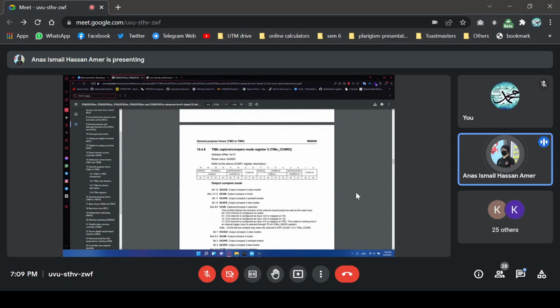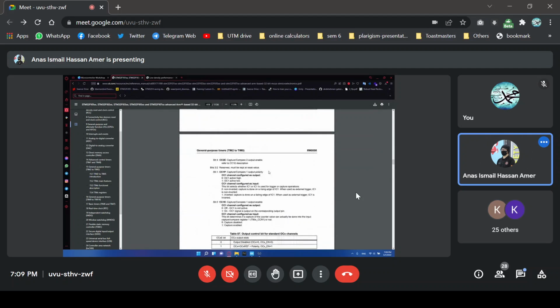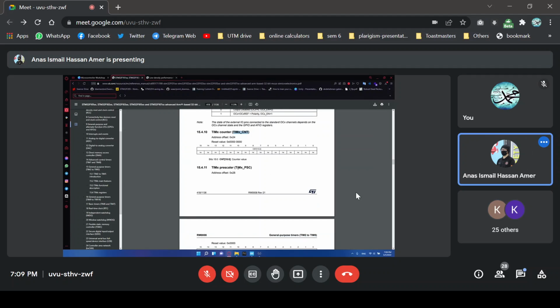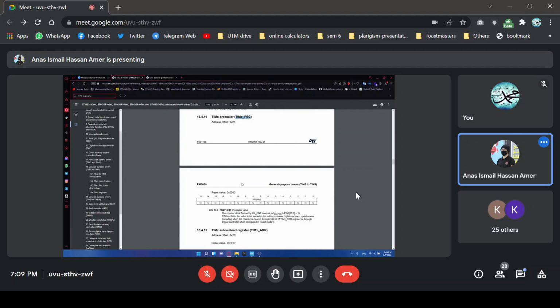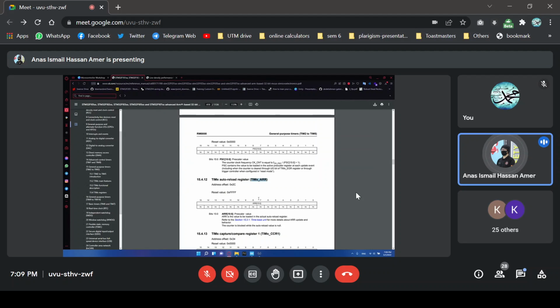This is input capture mode. This is the output compare, and so on. This is the timer count itself. This has the timer count currently. Let's say we set the period to 20K. If you read this at any point, it would be any value between 0 and 20K, depending on the count. This is the prescaler, which is PSC. And then there is also the ARR, which stands for auto reload register, which is also used for the period. So this is the period register.